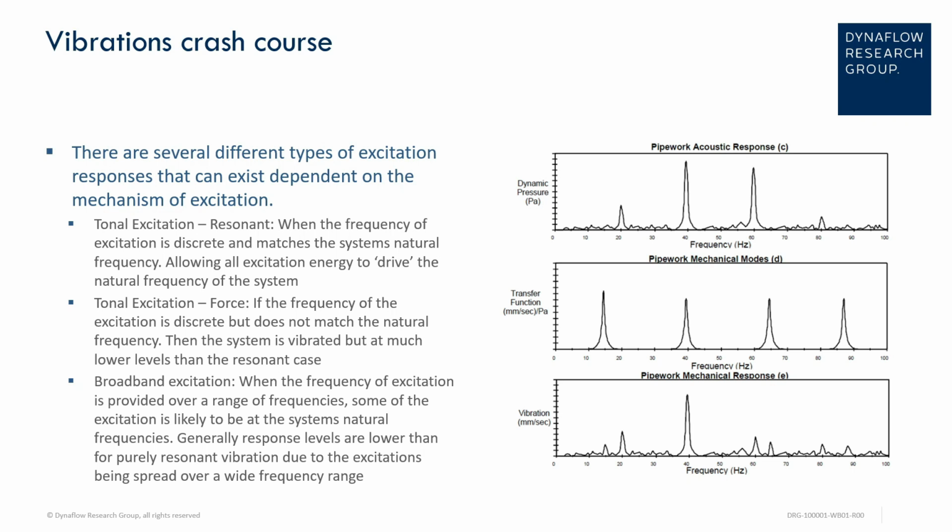Lastly, there is broadband excitation. This is when the vibrations excite a range of frequencies. Generally, the response levels are lower than the purely resonant vibrations due to the energy of excitation being spread over a wide frequency range.